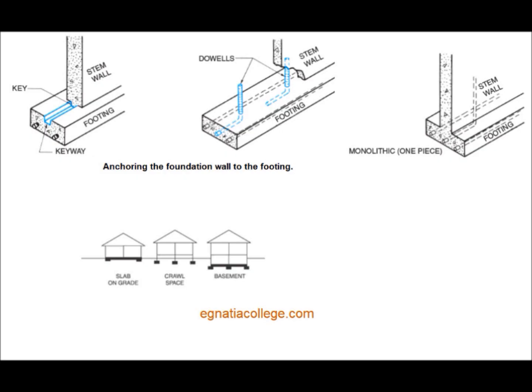If an 8-inch foundation rests on a 16-inch footing, the footing projects 4 inches beyond the foundation on each side. To lay out these footing lines, measure 4 inches from the building lines marked on the batter boards. Where footing lines cross to form a corner, suspend a plumb bob. Drive a stake under the plumb bob. Then, drive a nail in the stake to accurately mark the corner. When all corners are located in this manner, stretch a line between the nails to locate the inside of the